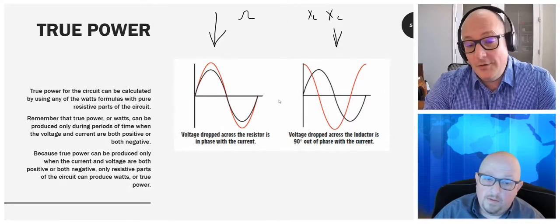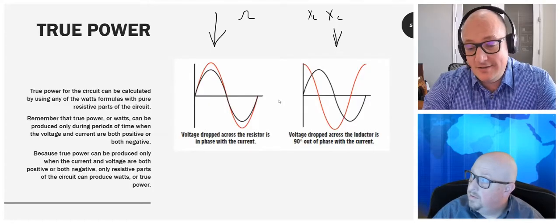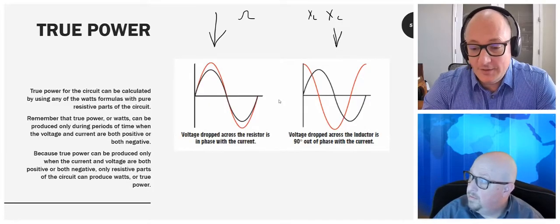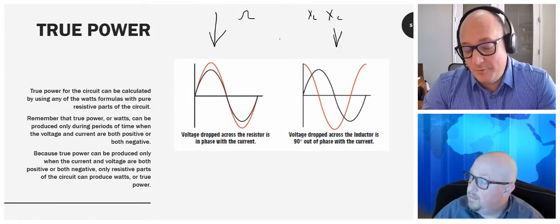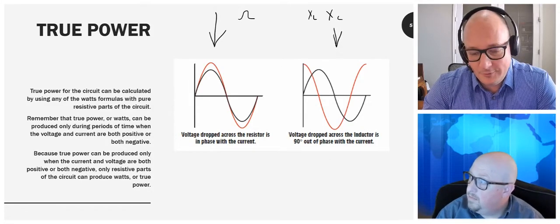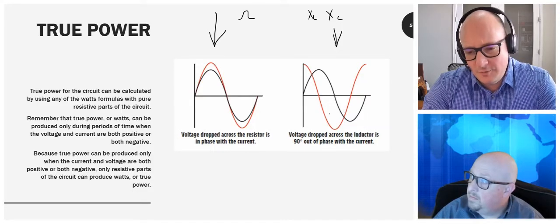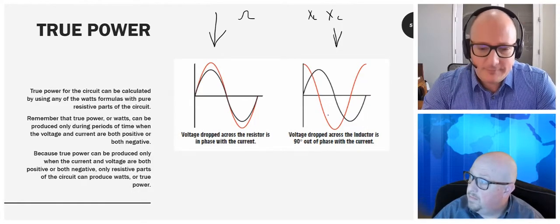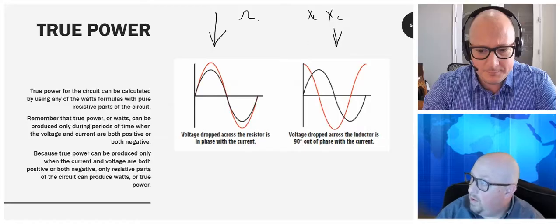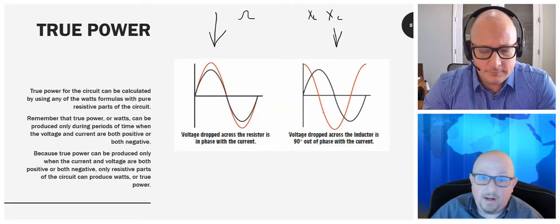But yeah, on the right would be like a high intensity discharge lamp, right? So metal halide, high pressure sodium, whatever it may be. But now you've got reactive components, and voltage and current are going to get a little out of phase with each other here. So my voltage and current are getting out of phase.